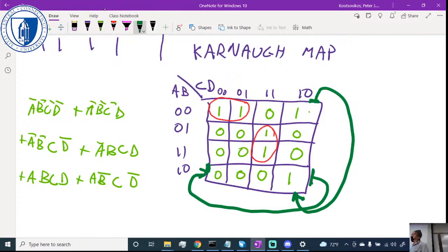So what that means is this one here is beside this one, and this one here is also beside this one. Okay? So you can think about this Karnaugh map as being on a donut, right? Because this one wraps to here, which gives me a cylinder, but then this end wraps to that end, so I bend the cylinder round to be a donut.